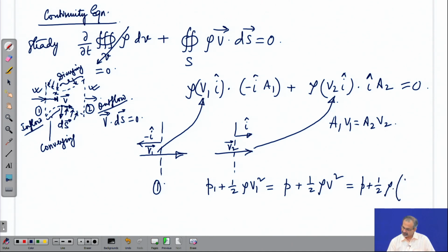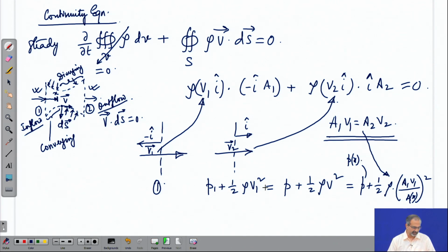and then you try to write that velocity at that section in a way like this, because we have come to know that continuity equation relates the product of areas and velocities like this. So, if you look at this, you have the x location incorporated, and you can also mention this as P x, because the pressure is changing along the location.